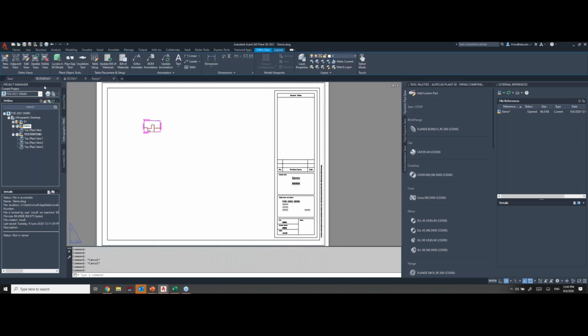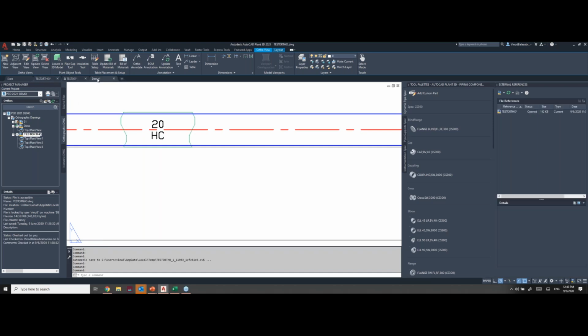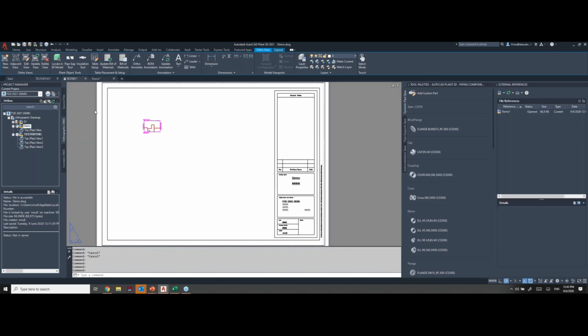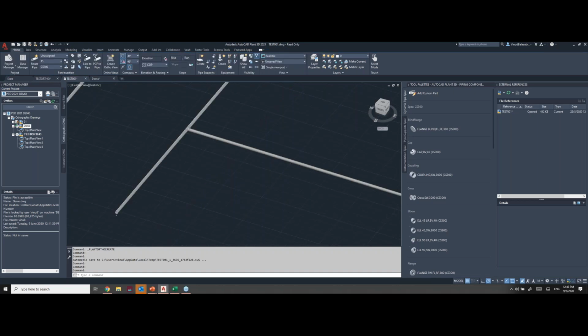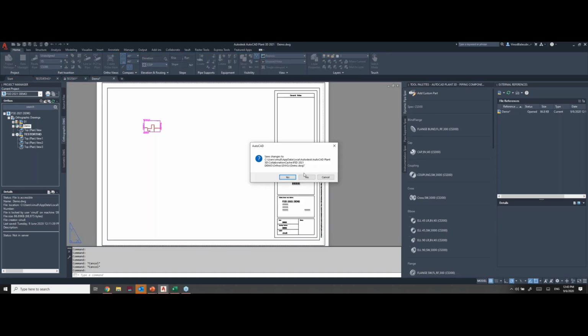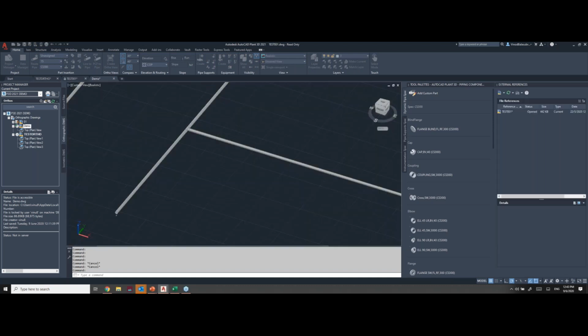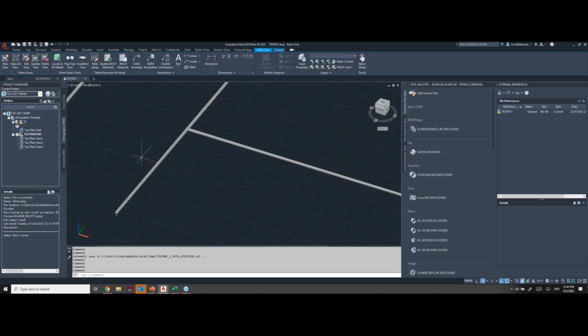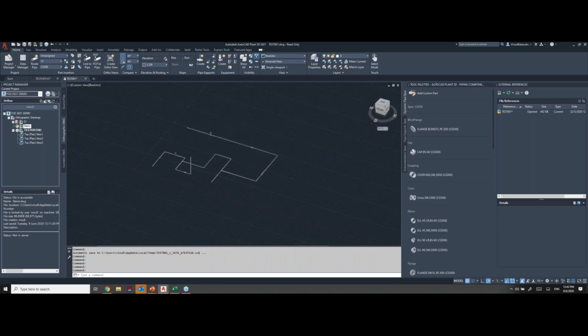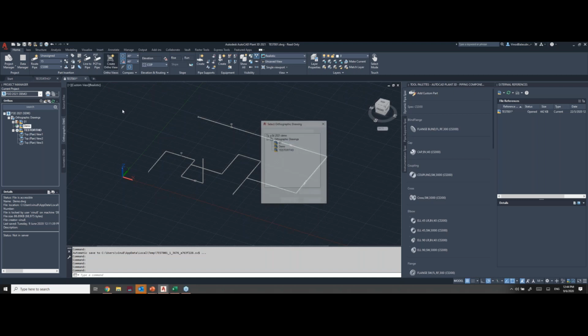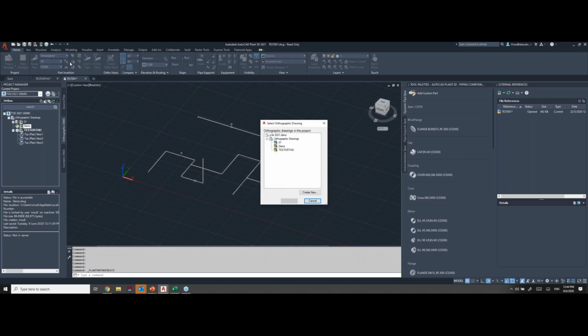Okay, good. Now let's go to the Plan 3D model here. I think I have it here. So let me go ahead and close all the demo authors just to avoid any confusion. Okay, now I have a simple model that I have just brought into Plan 3D. And now I just want to generate my ortho and see how the configurations that I made in the template show up. So one of the configurations that you want to watch is where I put the bill of materials and so on. So now you can see I can go to create ortho view under the home tab.